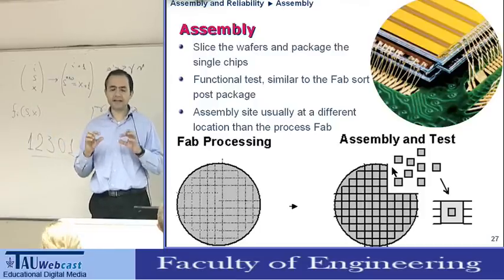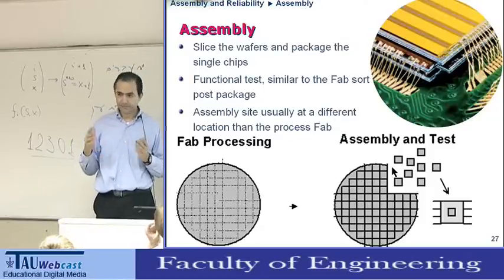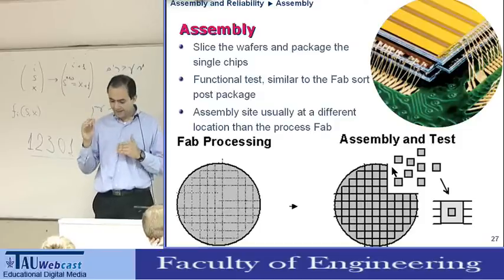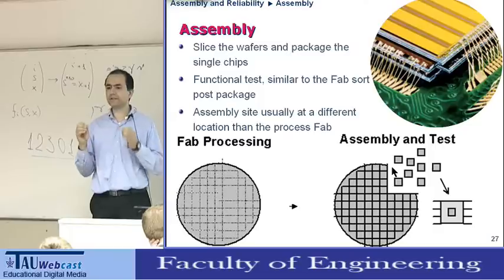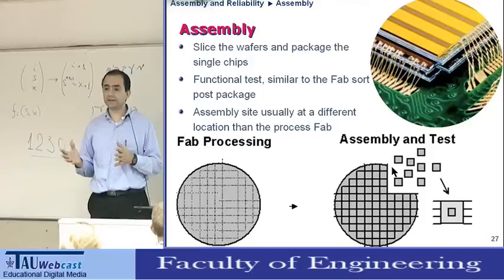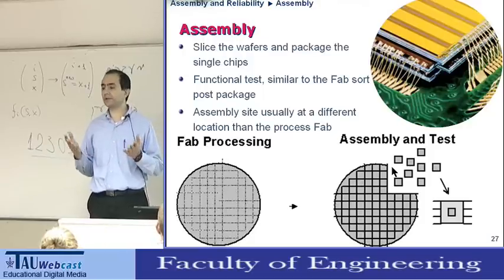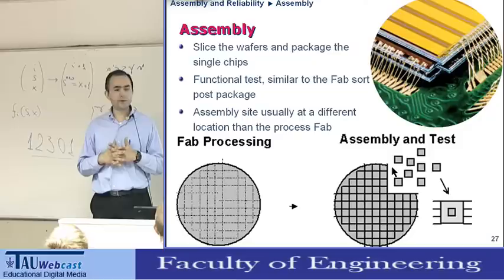The control limits allow us to find out any control issues in the line. For example, if a layer is too thin or too thick. And the dispo limit tells us that the actual value of this transistor or this resistor is too far away from what the designers wanted, so we decide to scrap the wafer, to throw it away, because we cannot guarantee the electronic performance of the chip itself. Before we go for a break, any questions?